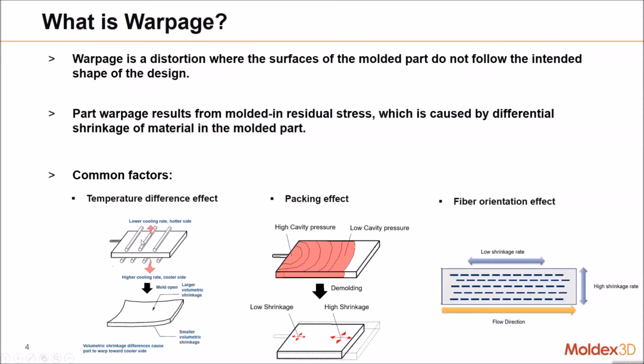However, there are only 3 cooling channels at the top side. So the hotter temperature accumulates on the top of the part. Therefore, we can predict the part is deformed into a smile shape, just like the picture below.